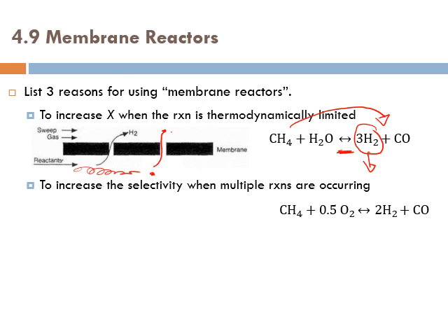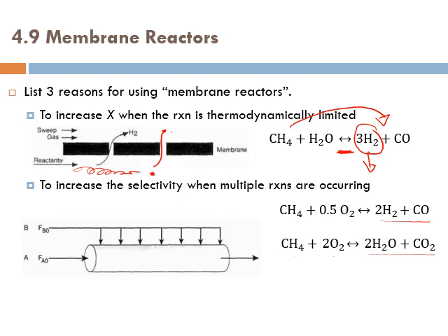So I'm doing reforming of methane through partial oxidation, and I'm still producing the syngas that I'm interested in. But what could happen? In the presence of oxygen and methane, combustion could occur, and you can simply waste the methane by combusting it. Let's consider this entrance here of the reactor.